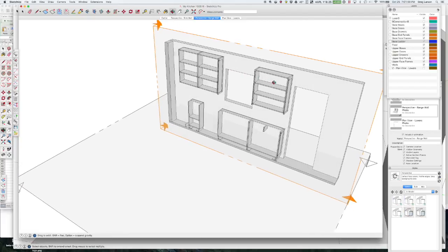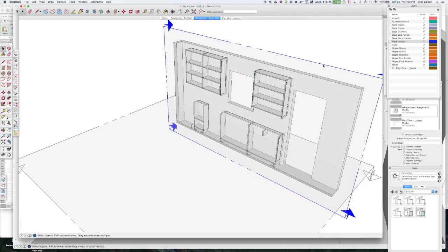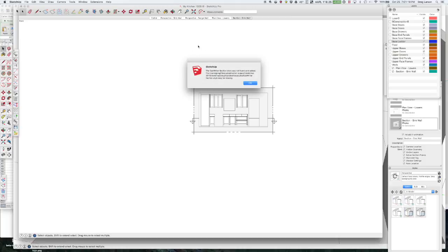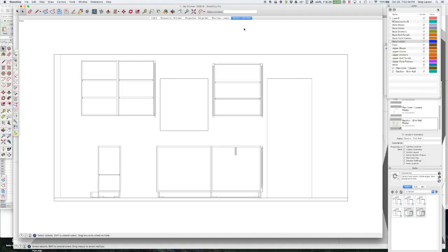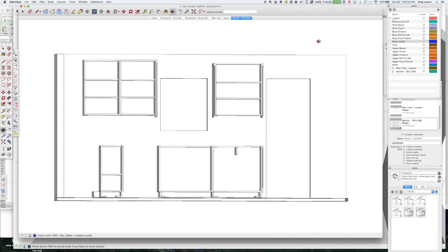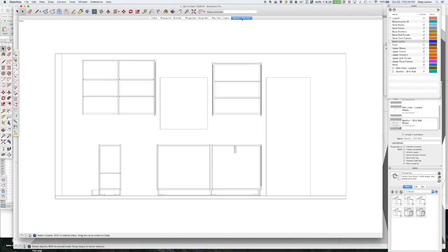So same thing. We don't want to see all the hollow in there, so I'm going to select this section plane, Draw, CabWriter, Create Section from Section Plane. We're going to call this section sink wall. Again, the style's missing, but we're going to ignore that. So we have a section for our sink wall here. You can see I can move it around, but it will always get me back. Right, so we've got a couple sections. We've got a plan view section.